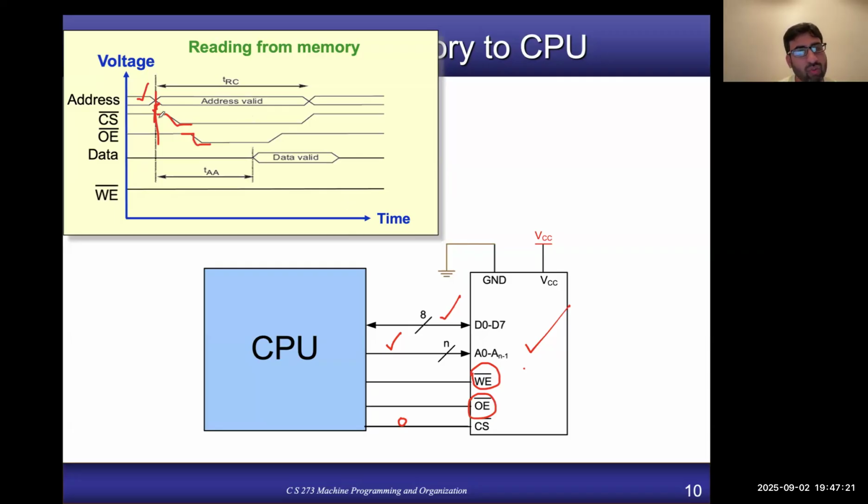And same is the case also for the chip select. So you can also again ask, why can't we make the chip select and output enable active low at the same time point here? Why is there this gap? Again, the same reason, that it takes some time for the memory chip to sense the low value of the chip select. And then once you have applied all the signals, it takes some time, and after that the data will become available on the output bus.